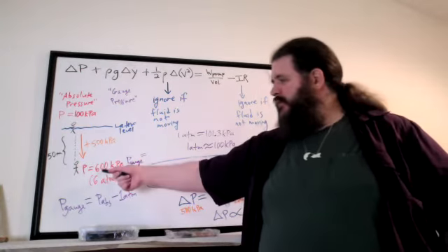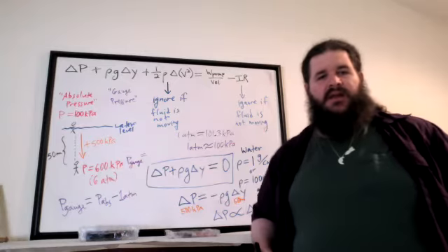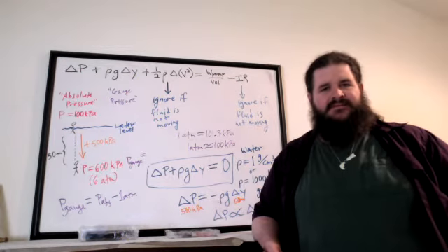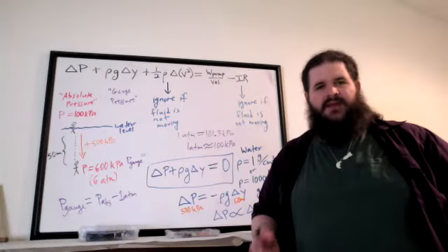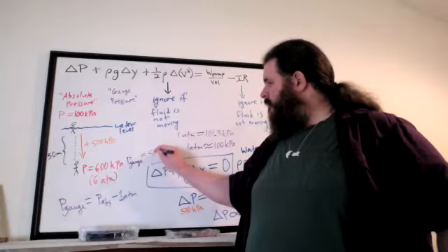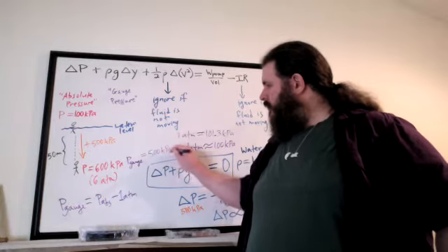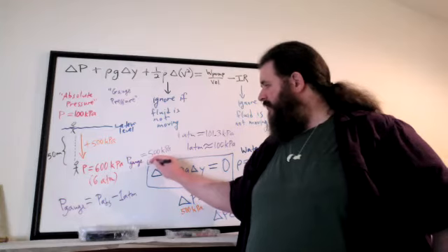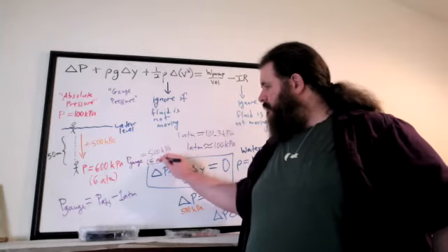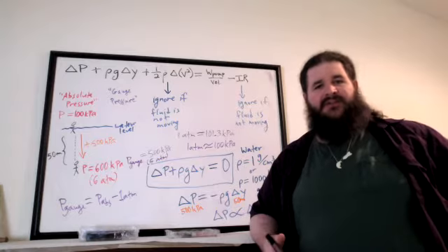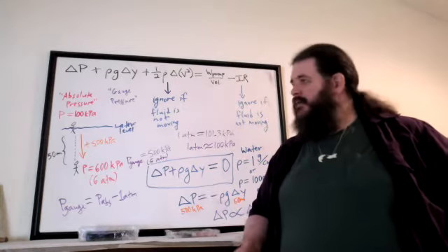The actual absolute pressure is 600 kilopascals, but how much above and beyond 1 atmosphere is that? Yeah, it's 1 atmosphere plus an extra 5 atmospheres. So at this location, we'd say the gauge pressure is 500 kilopascals, or 5 atmospheres. That doesn't mean your pressure is actually 5 atmospheres. It means your pressure is 5 atmospheres more than atmospheric pressure.